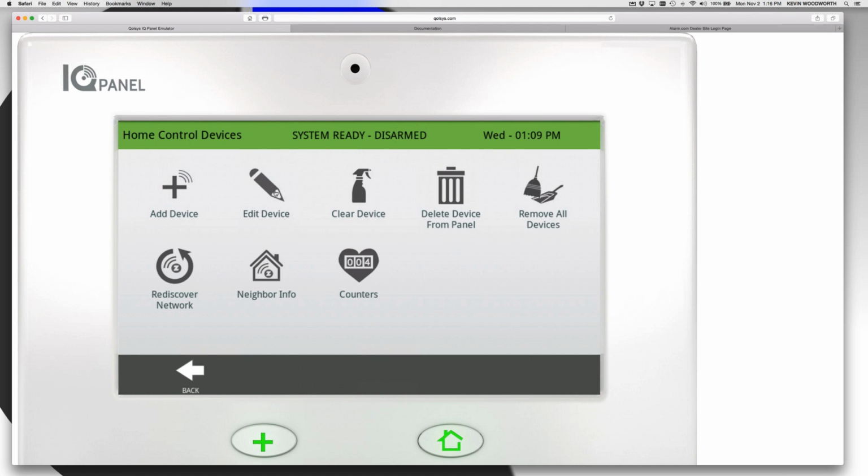And that's what a mesh network is. Understanding that about Z-Wave, that it's a mesh network, that it has a pretty small or short range, and that you want to add multiple devices, or what's called multiple nodes, in a network, will really help you design and install an efficient and reliable Z-Wave network. Knowing that, that's a good starting point. We're going to talk about some of the other nuances with Z-Wave here. That's what this top row is for. We're also going to talk about some of the tools we provided you, that's the bottom row here, to be able to design and troubleshoot Z-Wave effectively.